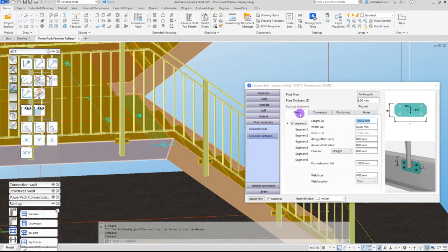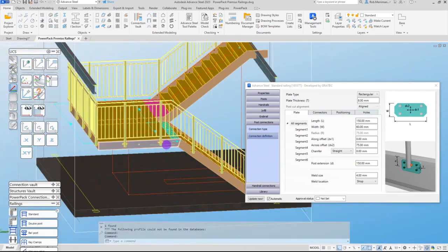We then want to come and move that plate. So what we want to do is look at DX2, I believe. So let's just say for now we want to drop that down 75 mil. Now I do have quite a lot to show you, so I'm probably not going to get these perfect. Oh, I might have to put it in as minus 75. Oh, there we go. Now that's worked quite well on segments 2, 3 and 4.